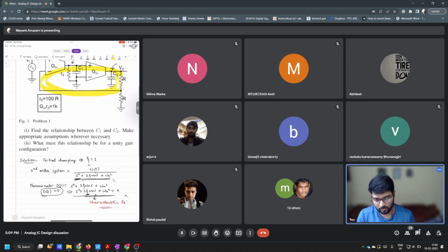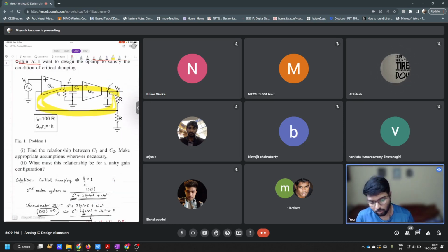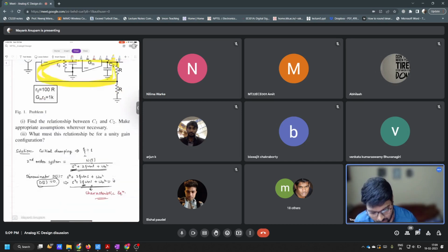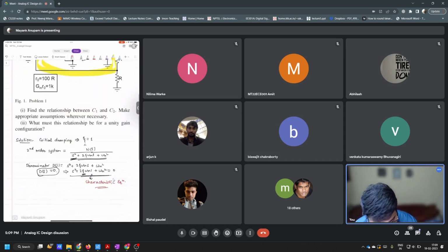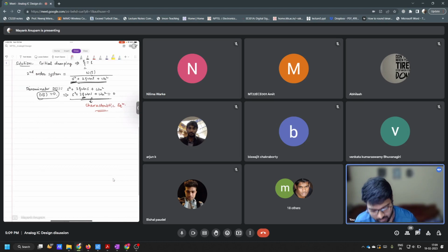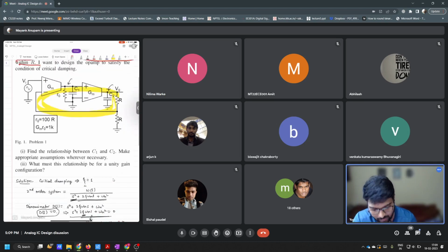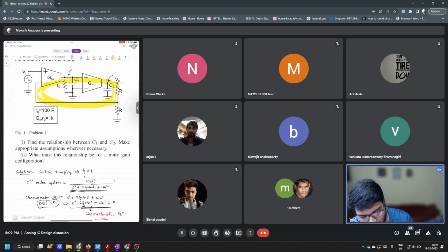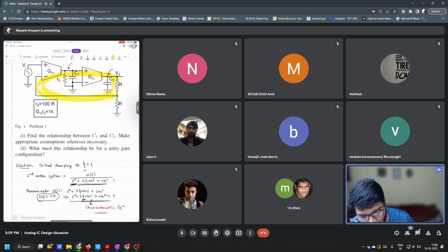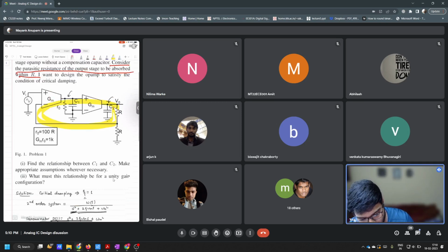Fine. So now what to do? How to ensure critical damping? Definitely you have to write some equations, right? So let's proceed. First I will simply write the equation of the whole closed loop system. So what will be the closed loop system equation here, V naught by Vi?